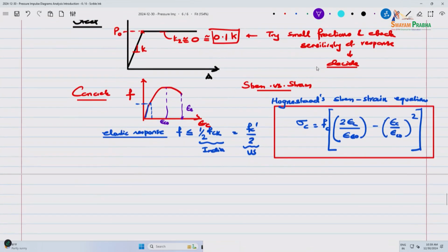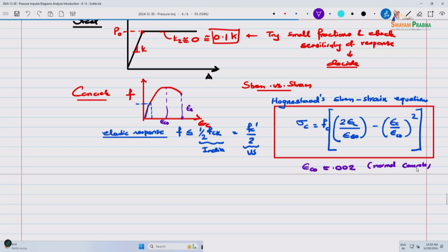So, typically epsilon C naught is considered for normal concrete. It may be a little different here, but peak is around 0.003 in some countries, 0.0035 in Europe and India probably. It's 0.003 there. And it's a non-dimensional equation, so this equation is valid for both systems.